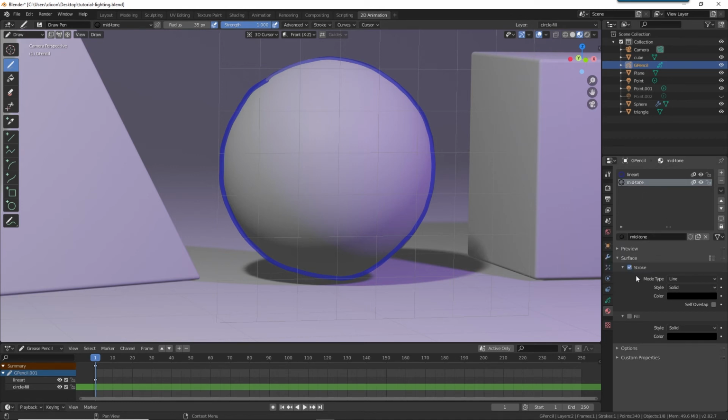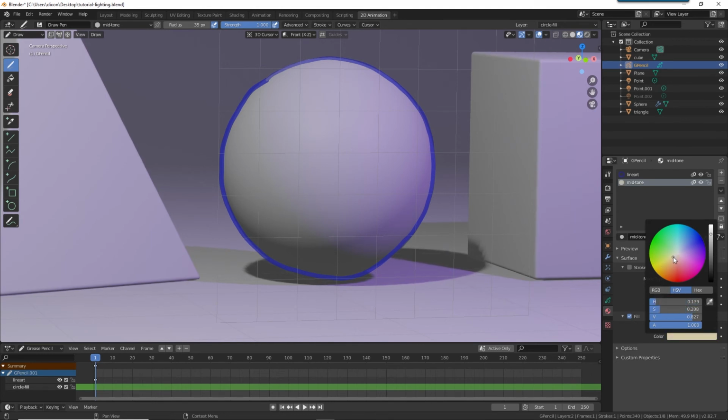So yeah, there are lots of different ways to name, and you'll see that by default it's selected stroke. Because this is a fill, we want to deselect that and select fill, and you'll see here again, as with the stroke, you can change colour. So we can make this sort of yellowy colour.